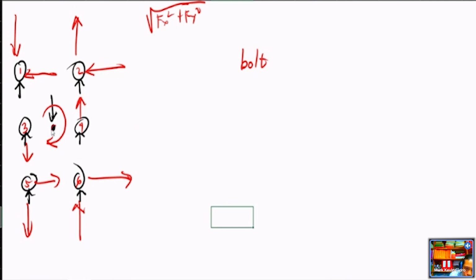The distance of this arrow and the distance of this arrow are the same perpendicular distance. So ibig sabihin, we can conclude therefore that the magnitude of this force and this force are the same since they are at the same distance. Tingnan niya kan, di ba? The magnitude of the force is just directly proportional to its distance from the centroid.